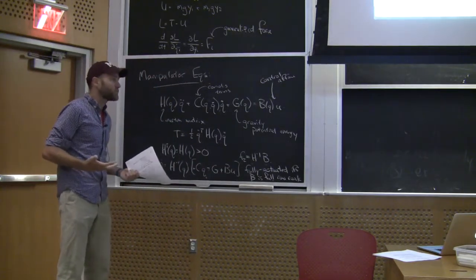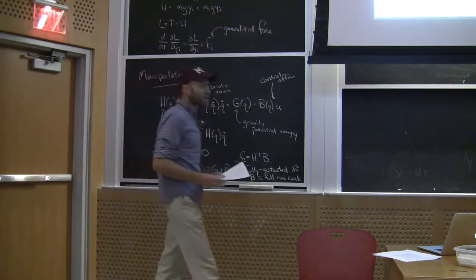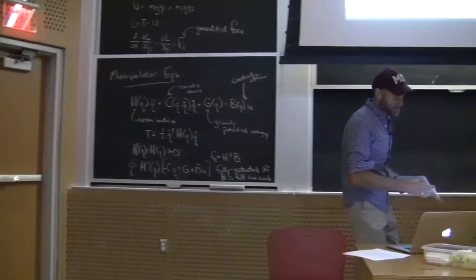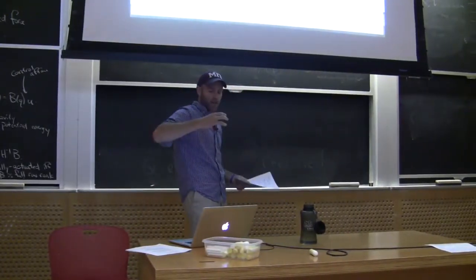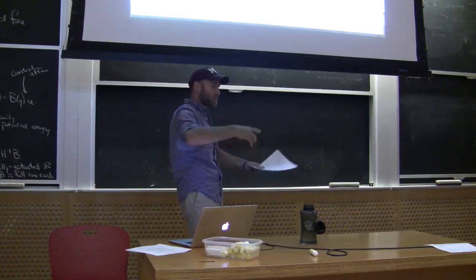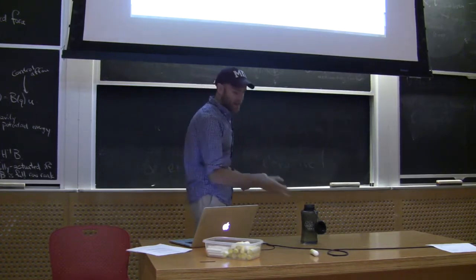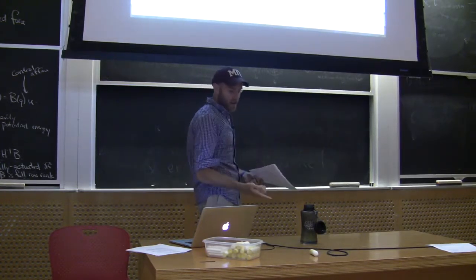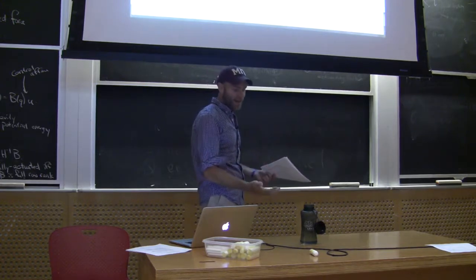We'll talk about that, okay? But a lot of interesting robots are underactuated. All interesting robots, let's say, are underactuated, right? So if I'm a manipulator, let's say I'm bolted to the ground, and I've got complete control. I can command any arbitrary accelerations. I've got huge motors. I can command arbitrary accelerations of my arm. But now my task is to pick that object up. That object has 6 degrees of freedom on its own, right? And I can't control them directly.